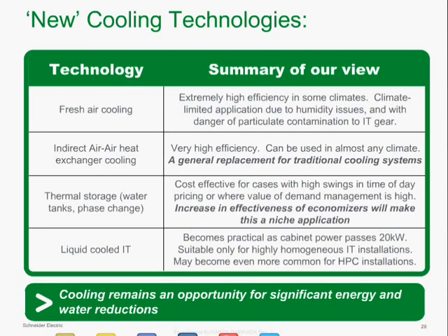We're seeing a few data centers out there that are using thermal storage, basically cold water, chilled water tanks for load shedding and peak shaving type applications. And then we're seeing liquid cooling in some high performance applications within laboratories and government facilities, but not really that prevalent yet in the common data center, and certainly not in the cloud and colo environment yet.